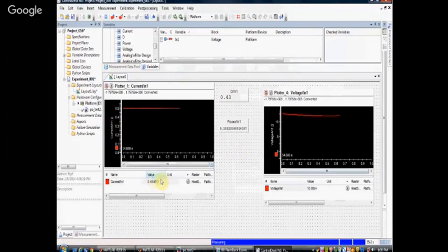So now I'll do it without MPPT, then with MPPT, and I can find the difference. The PMAX model I also have, so you can find the efficiency of the system. Next, I'll show you how to record the parameters also. In this itself, we can do the experimentation with partial shading also. You just take a small cardboard and shade some of your cells, and you can apply algorithms like GA, PSO and all, and you can do it.